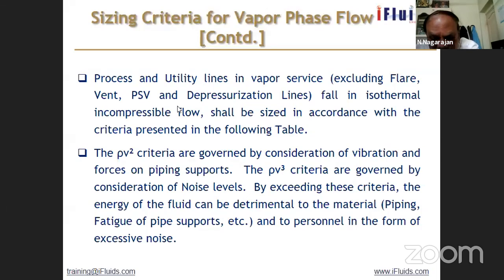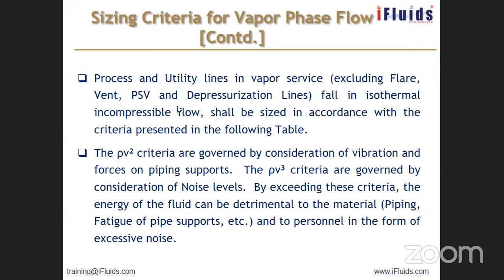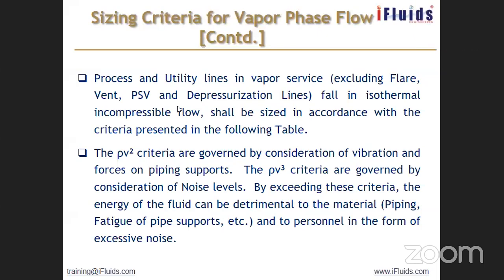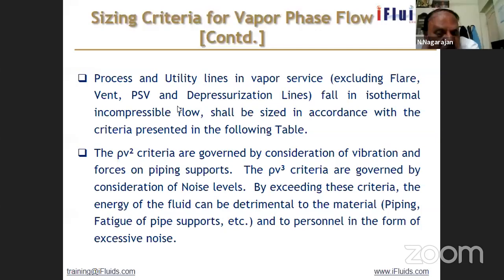So these are all the factors which we use when we design the piping, and we give these numbers to the piping engineer. He will do some analysis and provide the pipe supports. Pipes need support. They run meters and meters. You need to support. Even in household plumbing, you might have seen the plumber puts clips on the wall. When the pipe runs along the wall, he puts a clamp, say, every 3 meters, to arrest the vibration or movement of the pipe. So these two criteria are used to secure the pipes during operation.